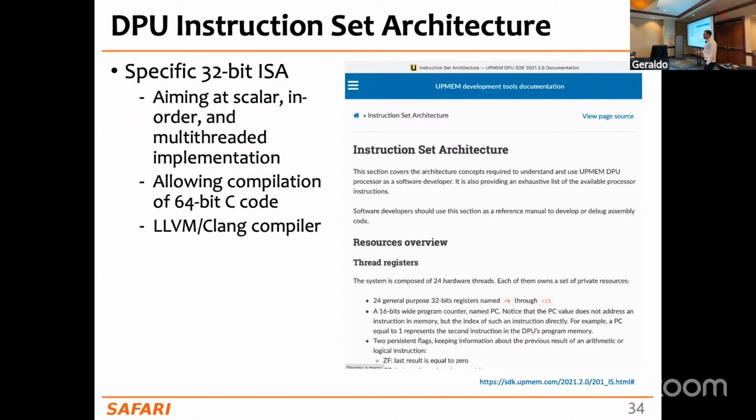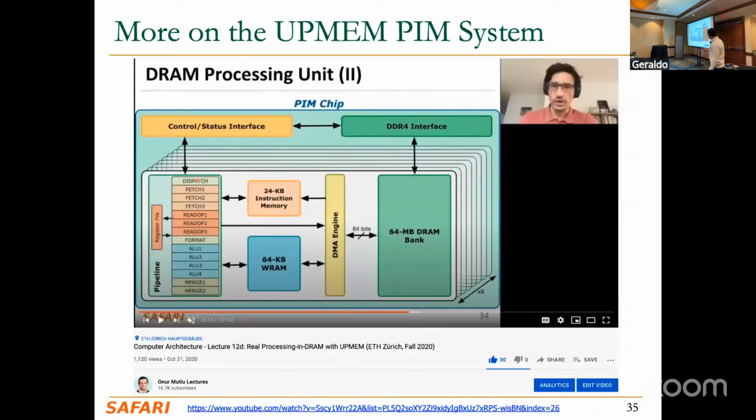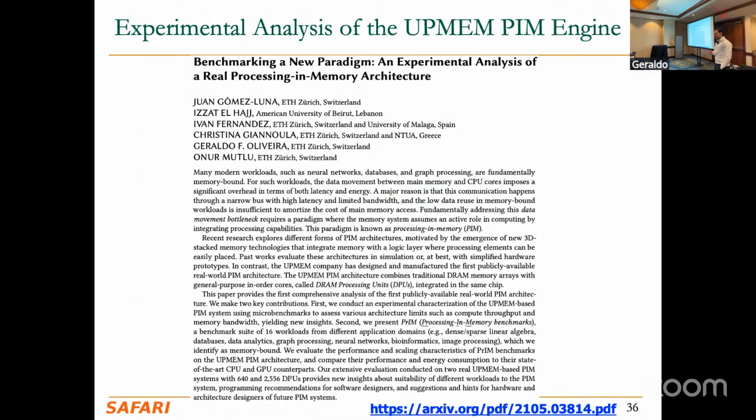They have their UPMEM-specific instruction set architecture, but it's quite, again, similar to some RISC instruction set architecture. And the UPMEM company has also put out an LLVM-based compiler used to create UPMEM binaries. We have some lectures online on the UPMEM architecture. So basically, after this architecture was released, we got in touch with this company and we got access to those systems, and we started doing a lot of experimental analysis on top of this real processing-near-memory architecture.